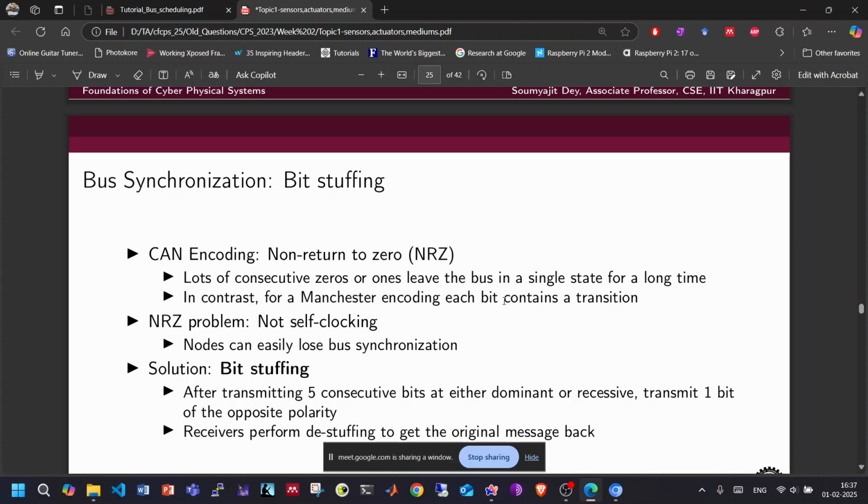In this case, there are different ways of doing non-return to zero. I guess CAN bus uses one of them. When I say different ways to use non-return to zero encoding, I mean you can either count a 1 when the signal is changing, when it's toggling, or you can count 1 when it's going to a high level and 0 when it's going to a low level or something like that. You can encode it like that as well.